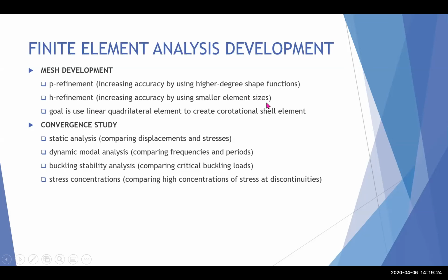For the H refinement, I'm going to compare the error with each element size. My main goal here is to create this corotational shell element. Hopefully next time I'll be able to show that. For the convergence study, I'm hoping to get through all four of these, but I'm going to start out with the static analysis, and then the dynamic, the buckling, and then the stress concentrations. So yeah, that's pretty much it.